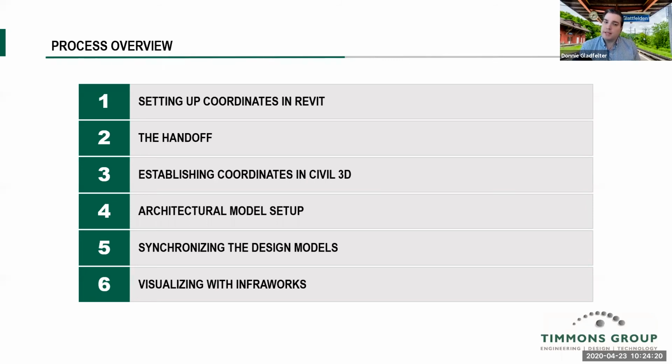I would still probably need some sort of pass-through model though to orient the architectural piece into civil. I know this is a hard one to talk through here, but you'll recall that when we used the shared reference point tool, we picked 2 points inside of our Civil 3D model that were specific to that building.